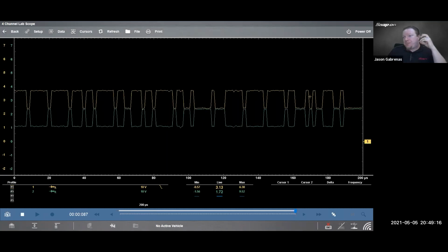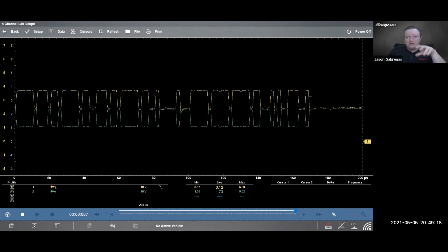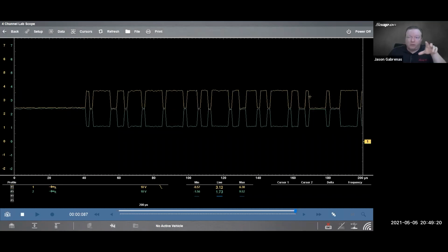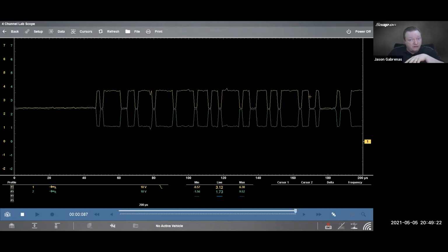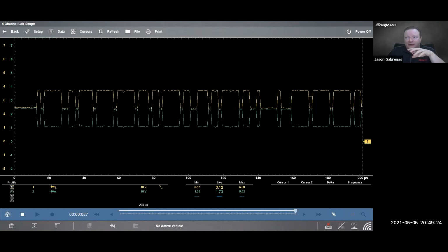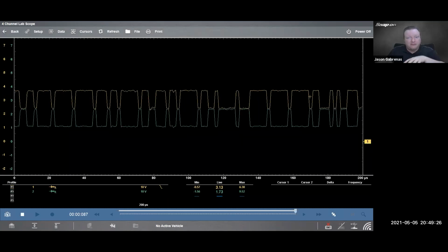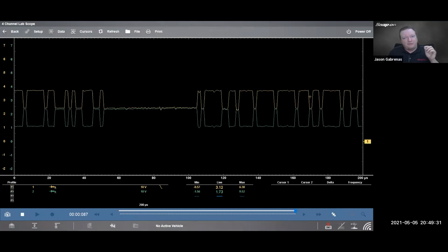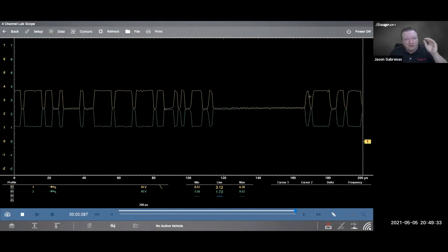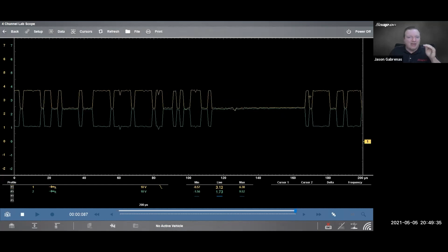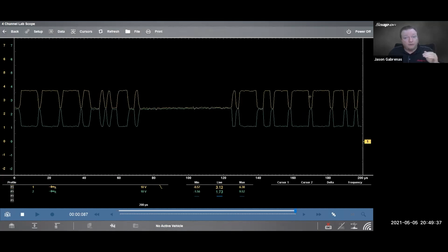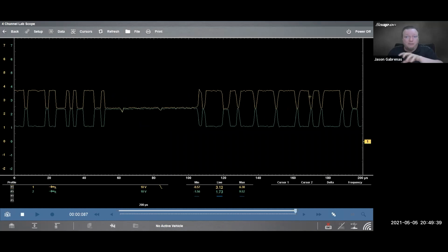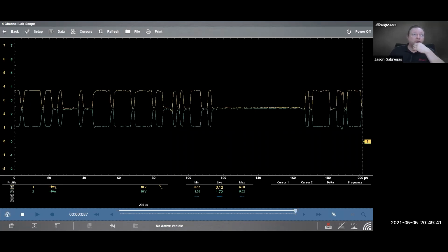So as I mentioned during the course, it depends on where in the circuit it's shorted. But by and large, those are going to be the main types of anomalies you're going to see in there. Sometimes it's not quite that full short all the way to ground either. So I might just have a little bit of a dip. Maybe I lose 0.5 volt or 3/4 of a volt or a whole volt. That might give you a little bit different result. I can't simulate that here, unfortunately.